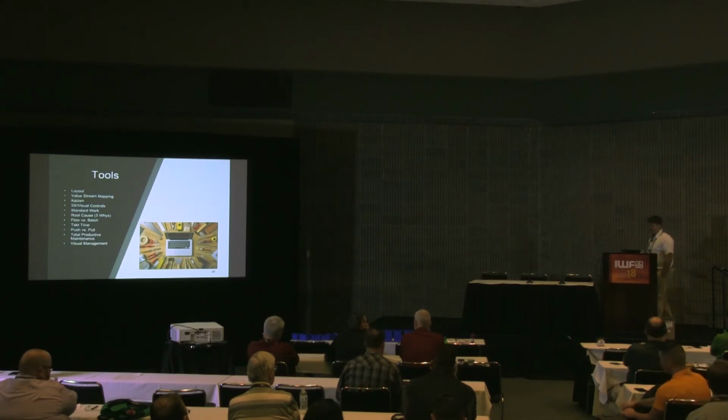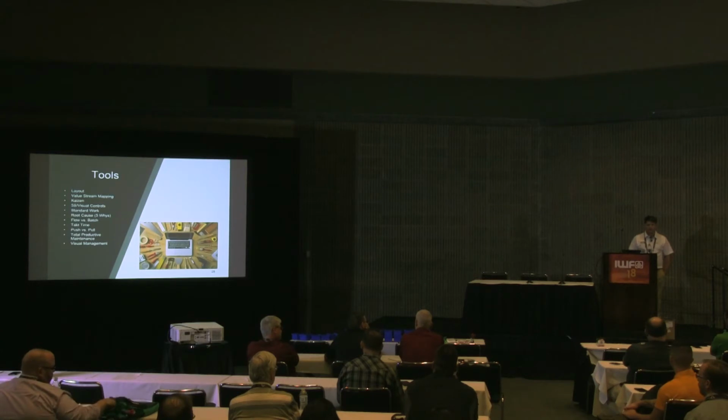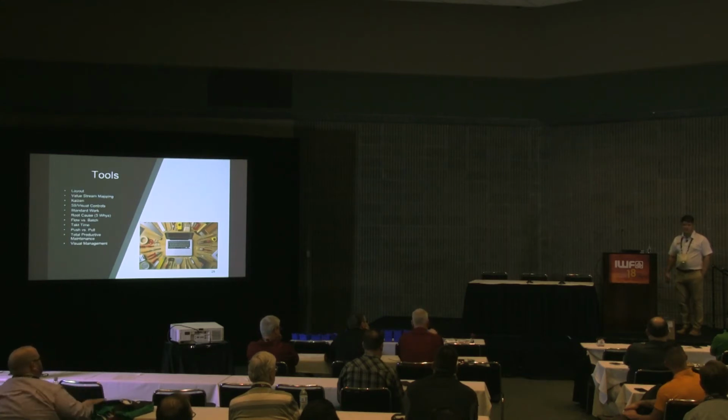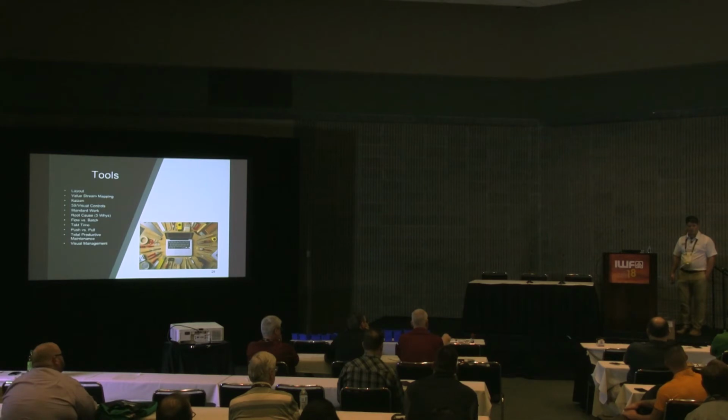Okay? Push versus pull. Instead of pushing it through the process like we're doing here, we can pull it with a Kanban type of operation. I have one ready, and whoever takes that piece, make one to fill it. I don't care if there's an order for it, fill it. If you run out of parts, let planning know. When you hit that reorder point, get more parts. Keep it ready. But like, yeah, but why would I make things that no one asked for yet? I say, well, you're already doing it, but you're doing it in work orders and you're putting them into stock, right? It's the same concept with a lot less parts and WIP.